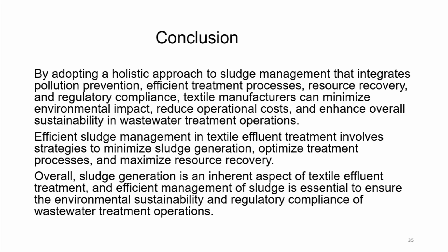So, if we look at the whole process, textile effluents have to be treated for removal of color, pH, temperature, turbidity, COD, BOD, TSS. When all that is to be done, some processes will generate sludge at different stages. Now, can we recover something reusable from that sludge?